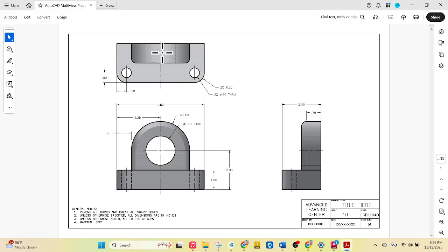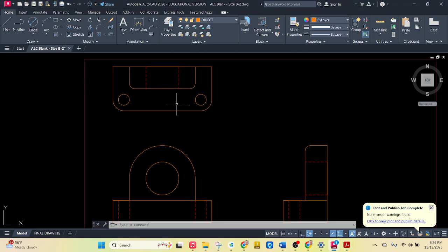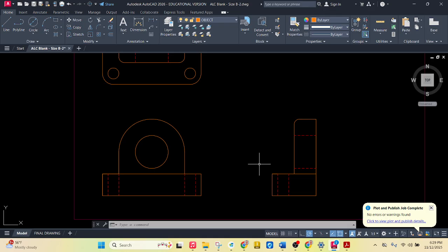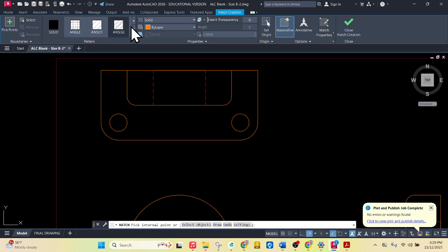Notice how I assigned anything that's facing directly upward the lightest gray. Then frontward facing for the front view is the mid, and anything on the sides, on the far right, and technically the far left would be the same in this case, is the darkest. That's on purpose, and we'll do that. First, anywhere that's totally flat and a solid color, we're going to assign those just to help guide us. So I'm going to go solid for my hatch tool.